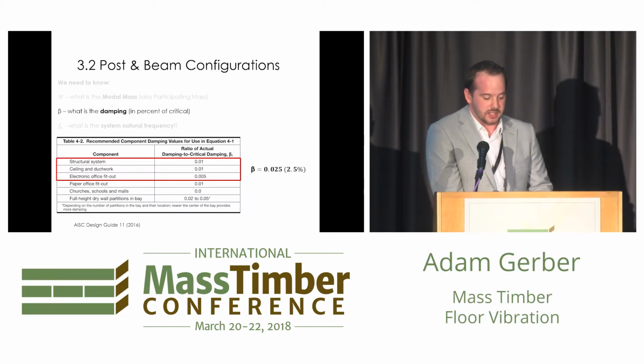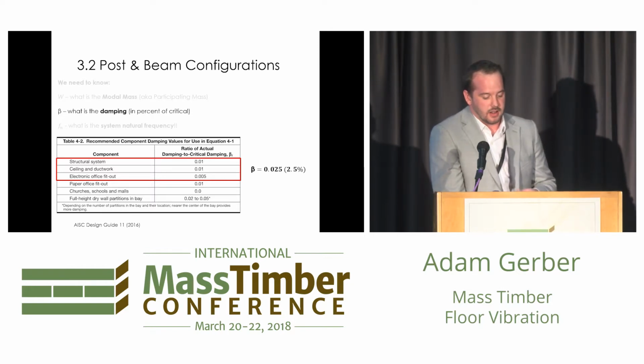The next part of the equation is damping. So again, it provides us good guidance on the different things that contribute to damping. Your bare structural system has some inherent damping, and then ceiling and ductwork and fit out ended up at around 2.5%.